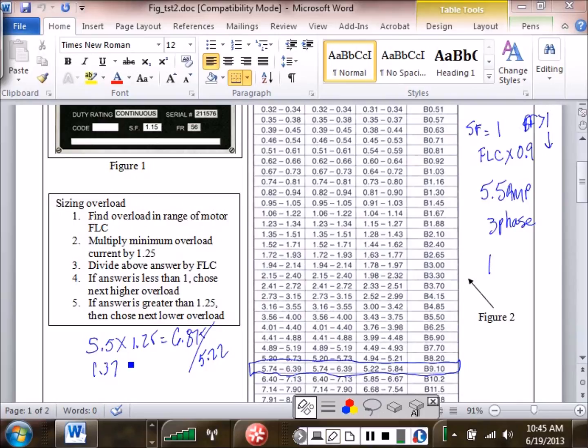That makes sense. All right, I'm sorry, I can't get run current anymore. And the motor's going to pull its run current if it's running at its rated horsepower. And we try to run a motor at its rated horsepower. A lot of people think if I need 30 horsepower of work, I can stick a 40 horsepower motor in there. But what happens is the motor becomes a lot less efficient.